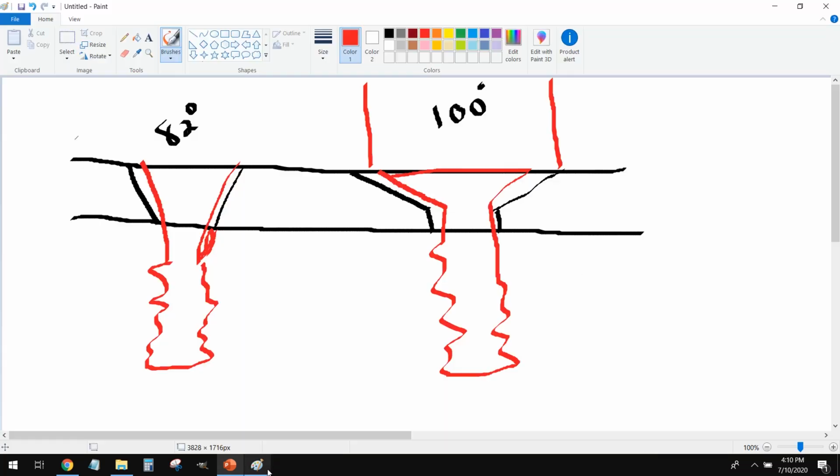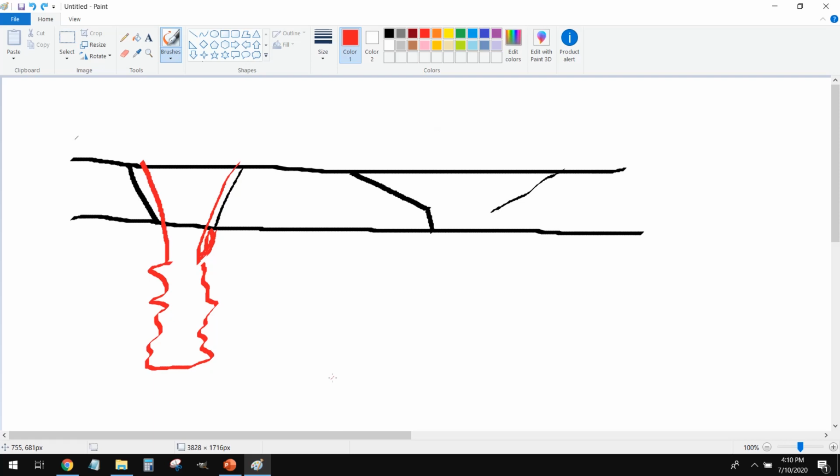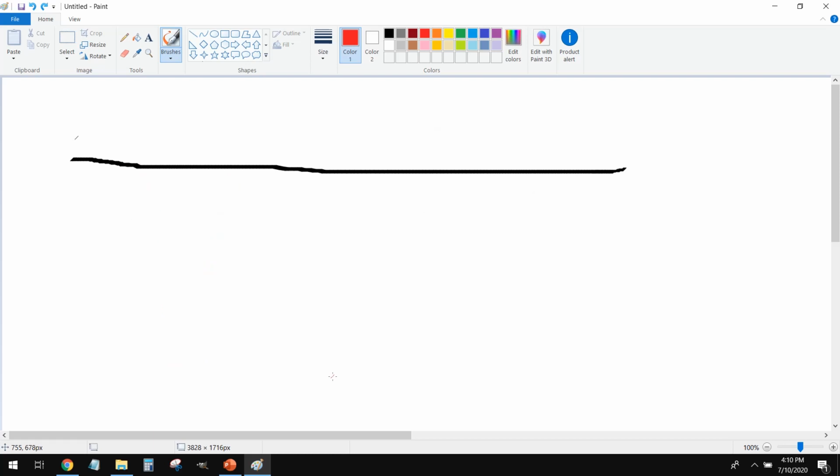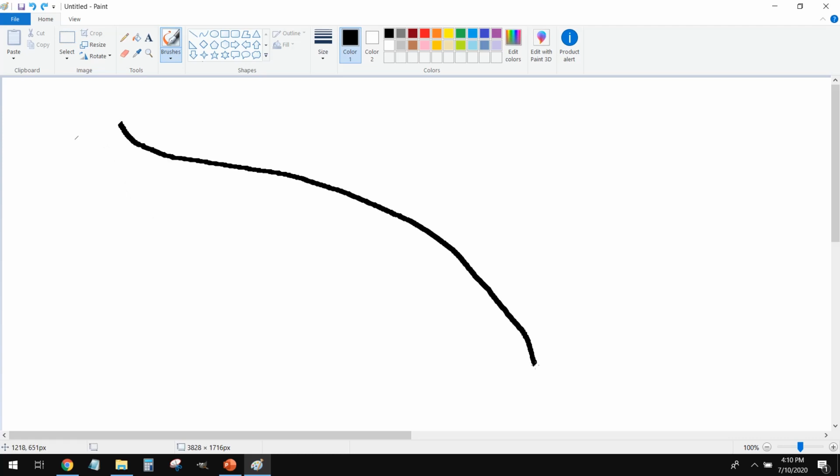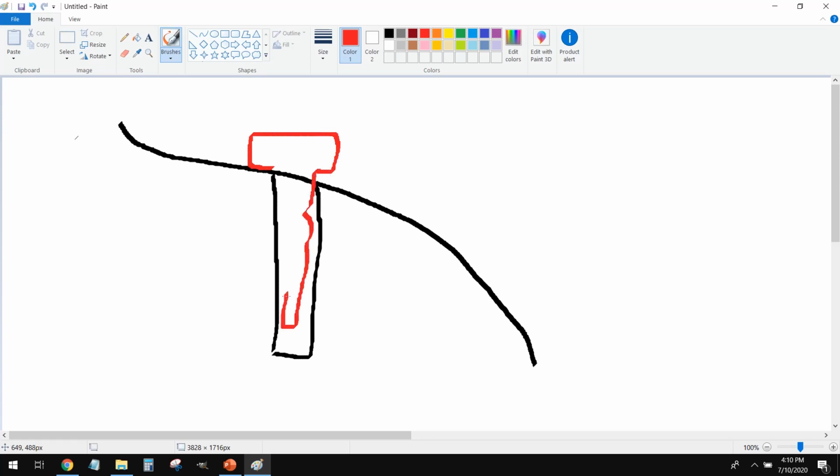You'll also hear something called a spot face, which is similar to a counterbore, but it's not intended to do the same thing. So picture we had a sloped surface like this, and we needed to drill a hole here. Well, when we go ahead and attach a screw to this, that screw head is only going to make contact at one point right here. This right here is not touching our piece. And what that means is we're not getting a full clamping force out of this screw.